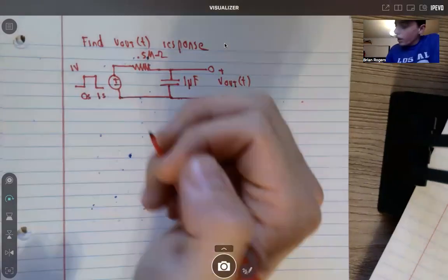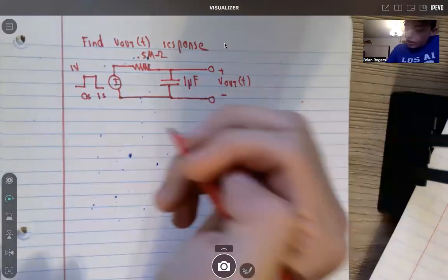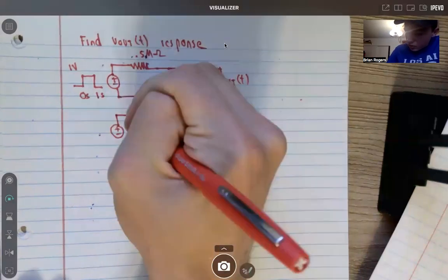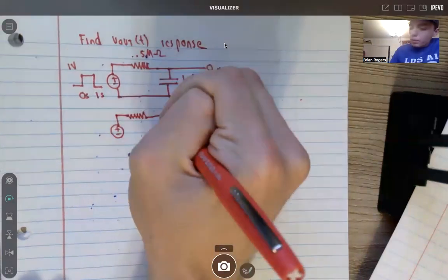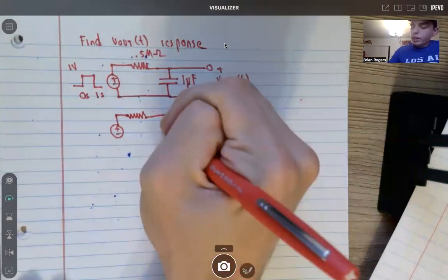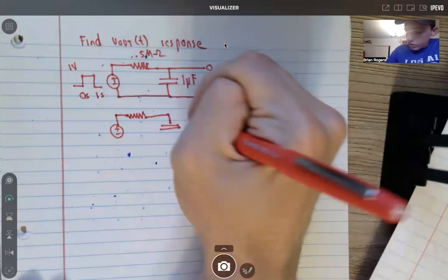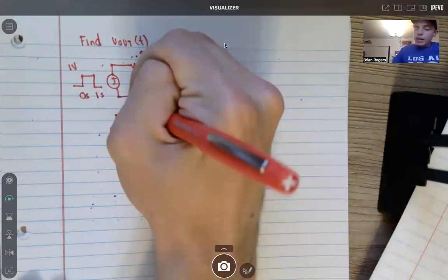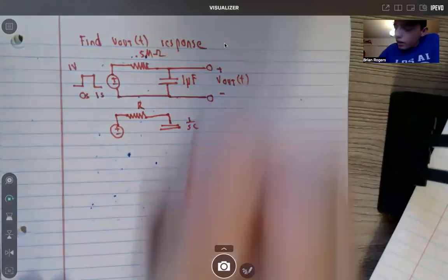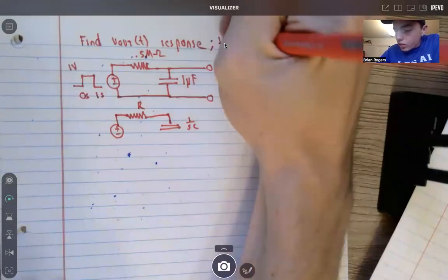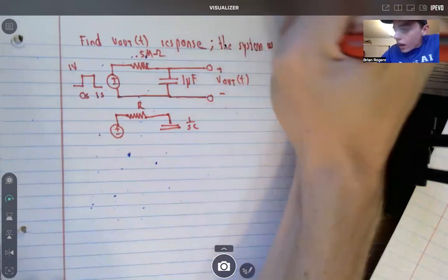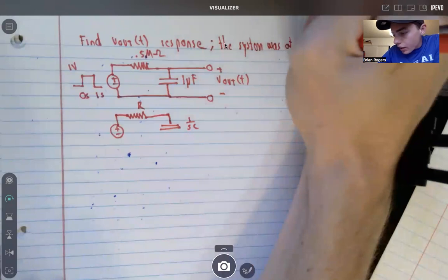And so what should be going through your mind initially is, okay, here's my voltage source, here's my resistor, that stays the same, but here's my capacitor. And remember, my capacitor is given by an equivalent impedance, which is 1 over SC, and then there's an initial condition. But it said at the top that the system was at rest at time 0.